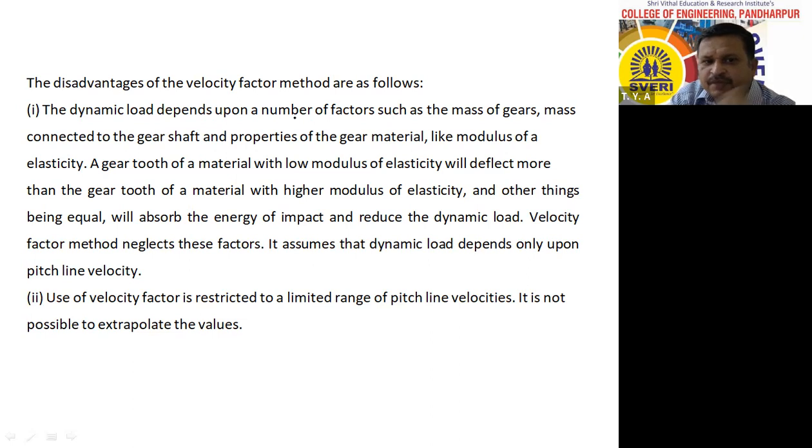The dynamic load depends upon a number of factors such as the mass of the gears, mass connected to the gear shaft, and properties of the gear material like modulus of elasticity. Young's modulus, you know, stress upon strain is equal to Young's modulus. A gear tooth of a material with low modulus of elasticity will deflect more than the gear tooth material with higher modulus of elasticity, and other things being equal, will absorb the energy of impact and reduce the dynamic load.